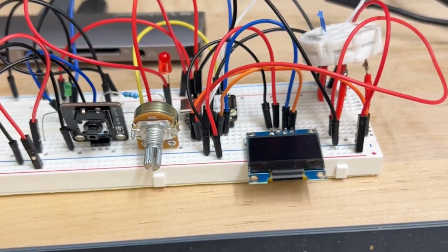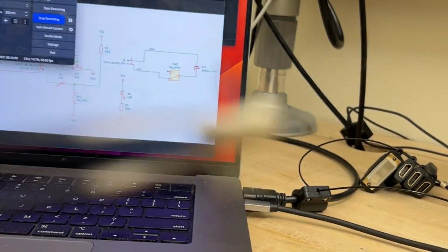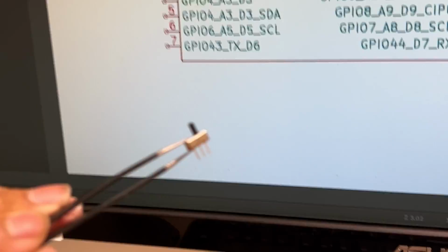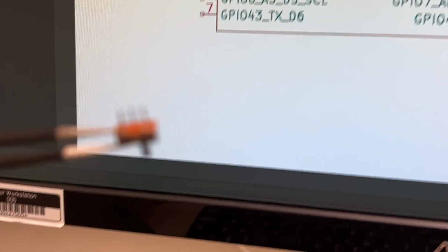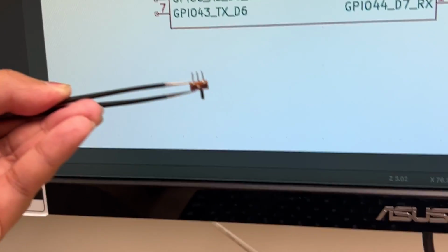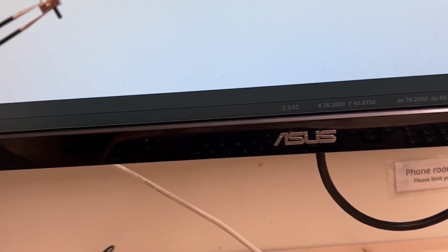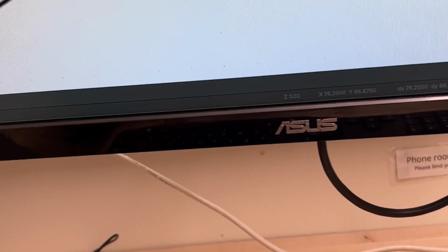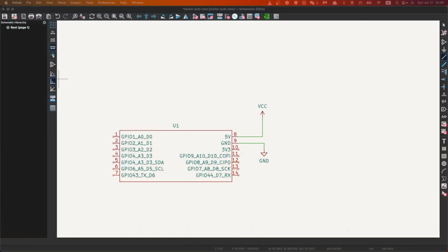So here is the switch we're gonna use. See it clearly? No, it's hard to focus with my camera here. So this is just a pretty simple 3-pin switch. If you are sliding it to the right side, the middle pin and the right pin are connected, and if you are sliding it to the left, the left one and the middle one are connected. So pretty simple, right? Okay, so we're going to use that as our switch. Switch back to my display here.